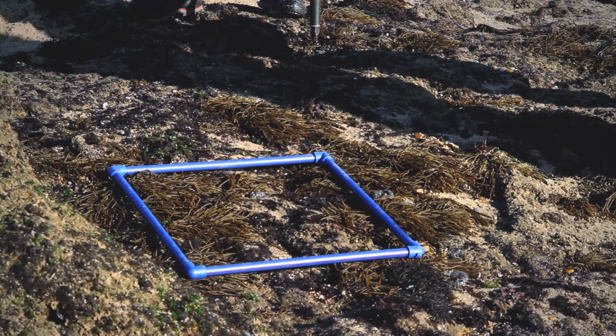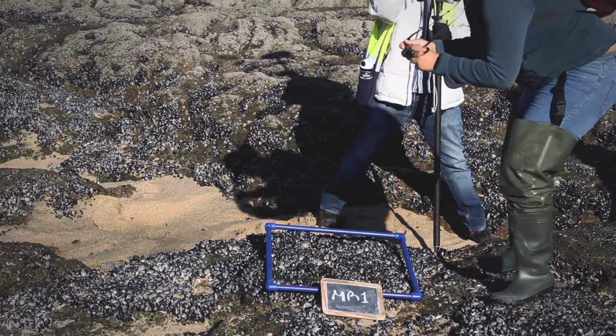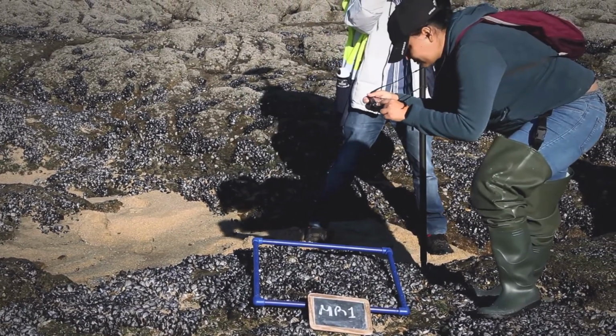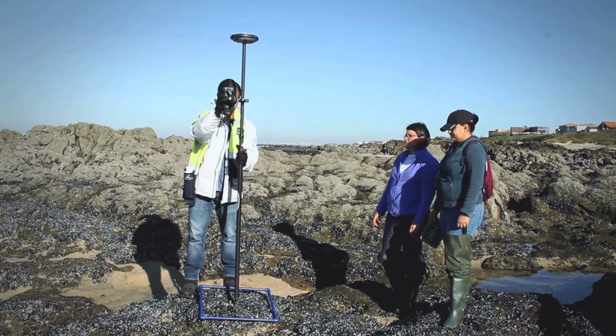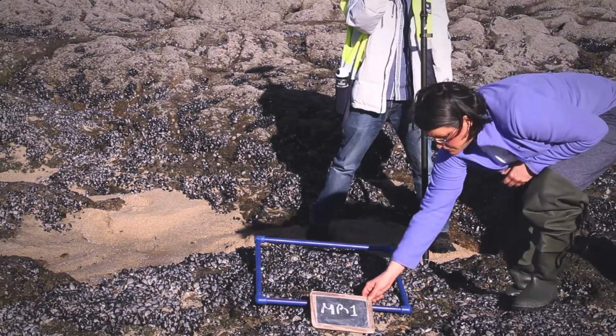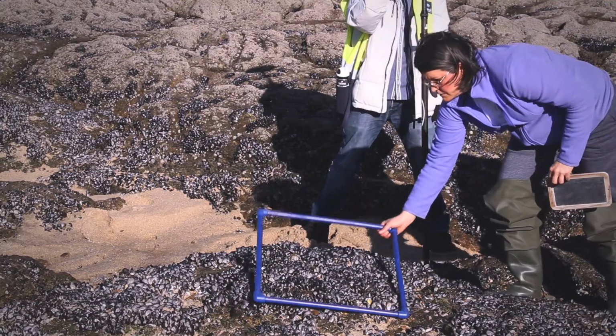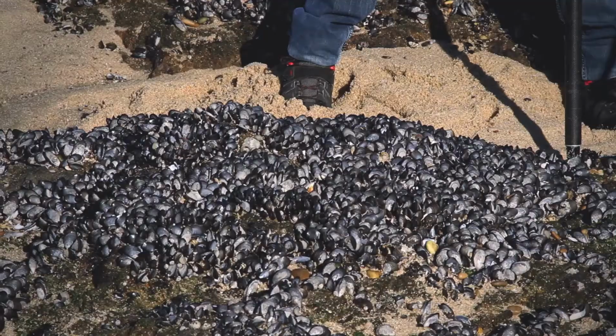Afterwards, we leave the quadrant on the shore until the flight is performed, so that when we are doing the photo interpretation, we can identify the quadrants and define the training areas drawing polygons. The second method also requires that frame, but instead of leaving the quadrant on the shore, we just use it to mark the area that will then collect the center of its coordinates. But then in QGIS, by buffer procedures, we're going to draw circles of 25 centimeters. In this way, we avoid having to place the quadrants and later collect them from the shore.